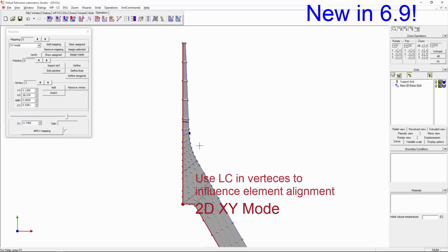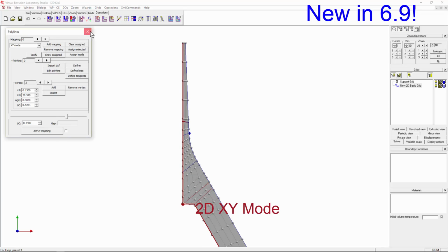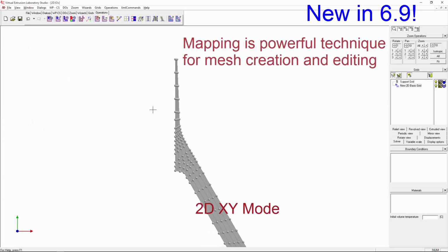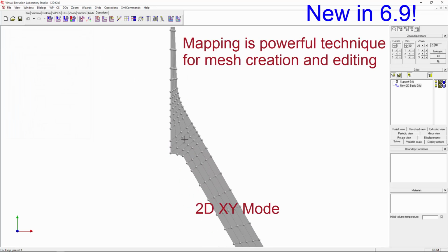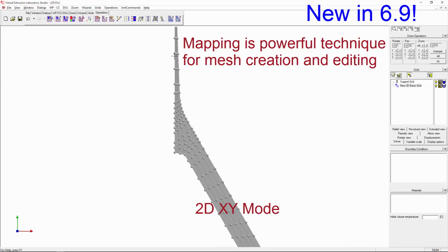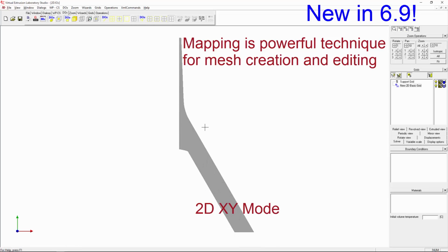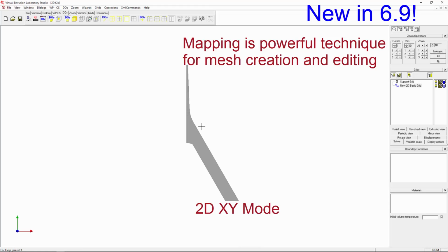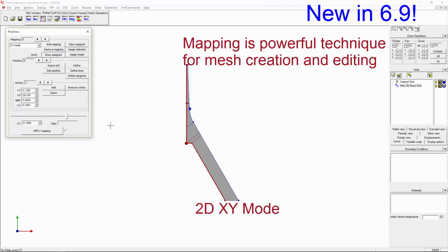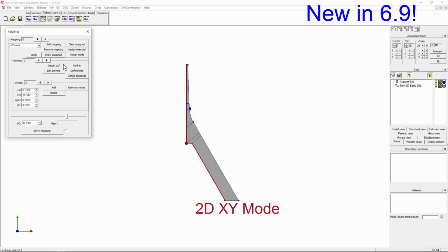Okay. Now, as you can see very easily, from one rectangle we've created a very complex mesh which you can now rotate, revolve, and use for either planar calculations or, with the revolved case, for 3D finite element calculations. Okay, so this is what the polyline parametric entry is for, and there are a lot of functionalities which we will slowly reveal and explain to you.